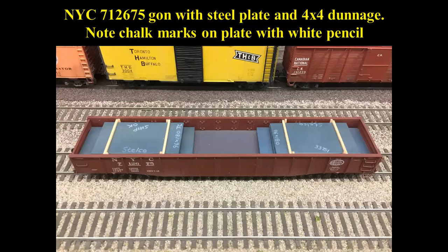for different customers. Just looking at some of the chalk marks, it says Stelco on it, okay to ship. There's also the size of the plate, 96 by 180, and a TC indicating that it's been torch cut to that particular size. On the right-hand side, there's a 6-digit number, which is the heat number of the furnace it was made in, so that they've been able to check the metallurgical qualities of the plate to make sure that it meets customer specification. And some minimal blocking in this particular car.